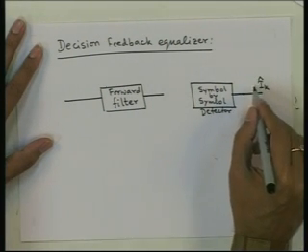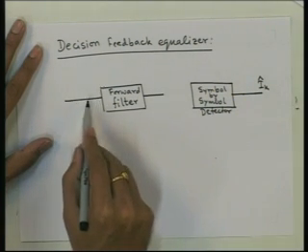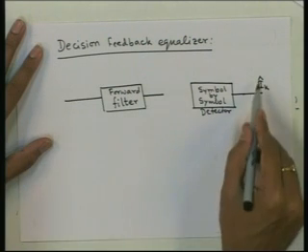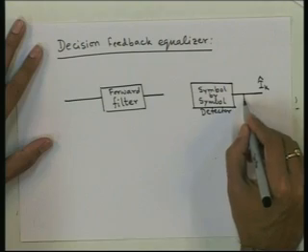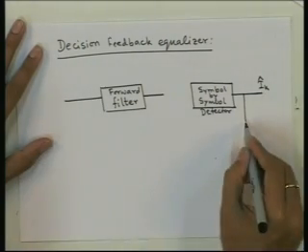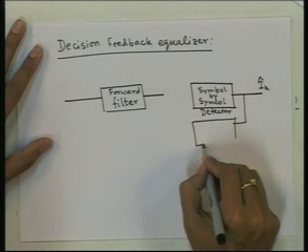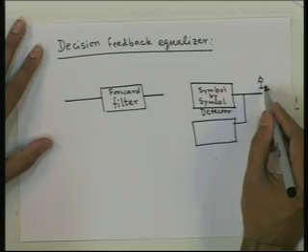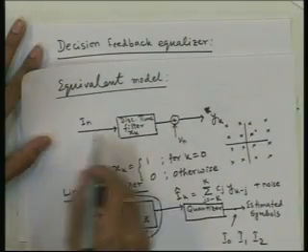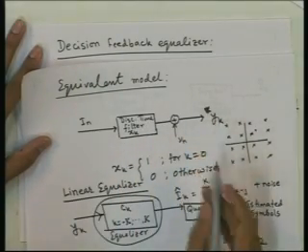After getting these values, what we said is that now the samples we are receiving here have some effect of these symbols which we have already detected. So, we will derive the effect of this on this signal, which is basically saying that we will pass this I k hat through the filter x k itself, because this I n sequence actually passed through x k to give us this signal.